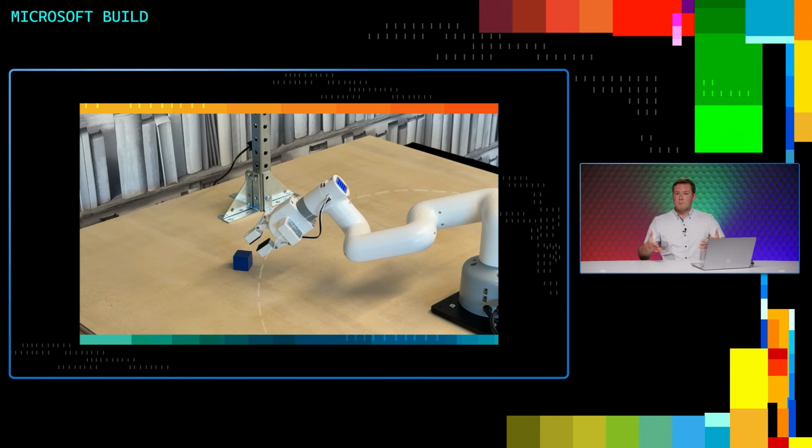Now, in our example, there are some things that we were interested in monitoring. One of them is the robot's span or reach, right? Our robot, of course, is very small, and it can only reach, I don't know, maybe half a meter or something. The field of view of the camera is actually larger than that. And so occasionally, you have the situation where the camera can see an object, and the robot believes that it's being asked to go pick or place that object, but it actually can't reach it, as you see in this image here.